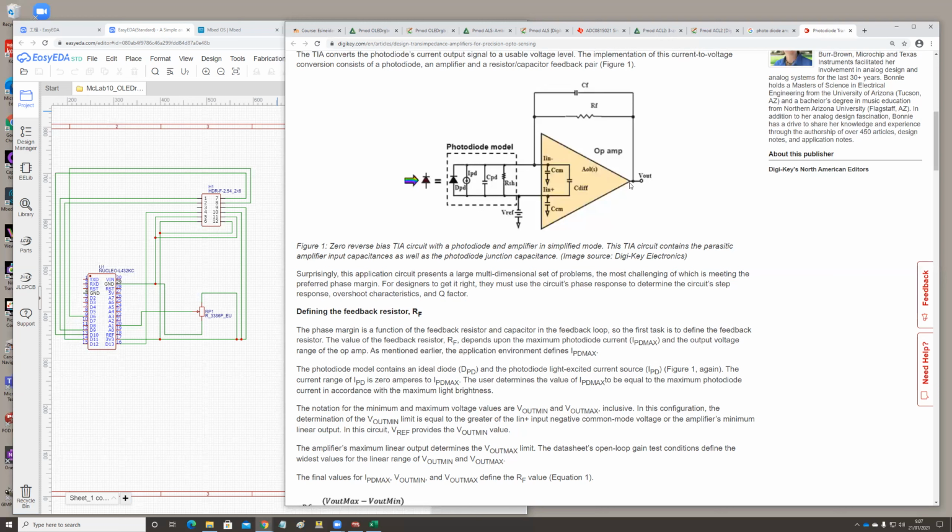And this voltage you could measure, for example, with the analog to digital converter. So you can measure the output voltage from here. The capacitor here is for defining how fast transients this photodiode is detecting.